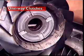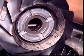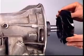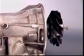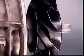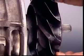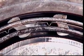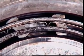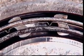In the Sprague-type one-way clutch, the inner race has a central spline. It locates on the stator support shaft to hold the race stationary. The outer race is part of the stator hub. It turns with the stator in the direction of engine rotation. Equally spaced sprags between the two races produce a wedging action to stop the stator rotating in reverse.